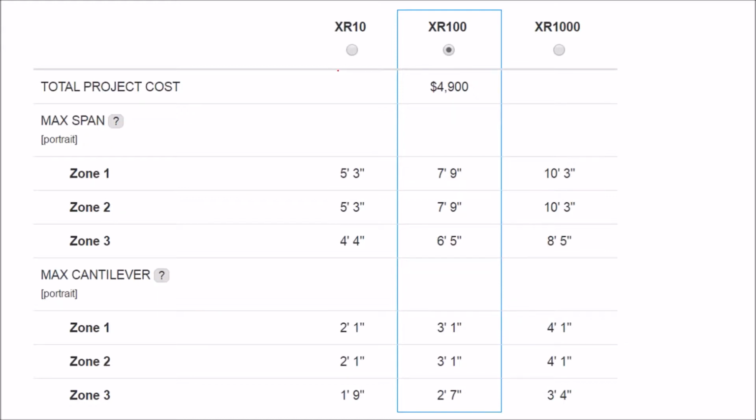Let me see my mouse here. Your rail thickness, you have your solar rail, and there's actually a little top channel in this rail for the clips to go into, and a little side channel for the roof attachments to go into. And so your clip is a bolt that slides into here, and then it has some wings on it. And these wings just clamp down on your module edges, and then you're running across your rail, and your modules get pressed down onto the rail.